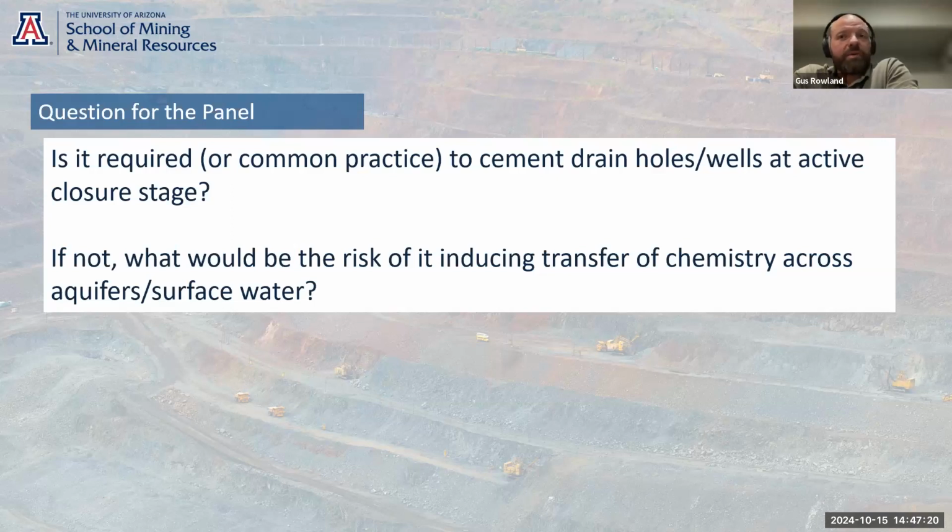I can't comment much about grouting wells per se. And the risk as far as underground mining goes tends to be more about the quantity of water than the chemistry of water. But in situations like this, we have seen some interaction of nitrate-laden shallow groundwater that is then interacting with deeper, better quality groundwater through ungrouted exploration wells.